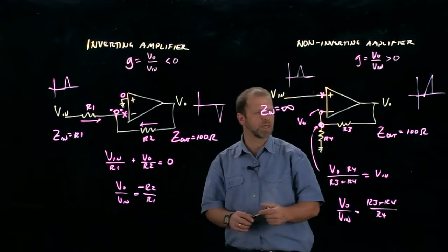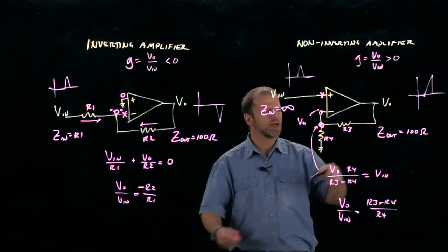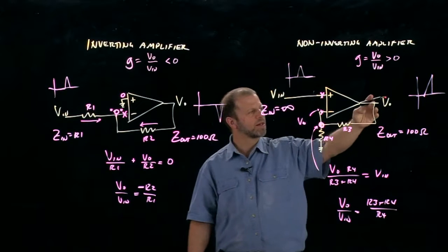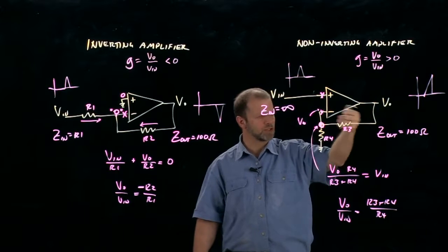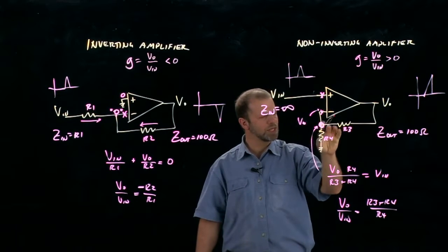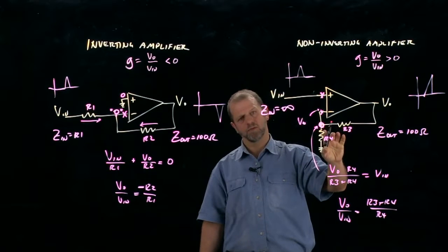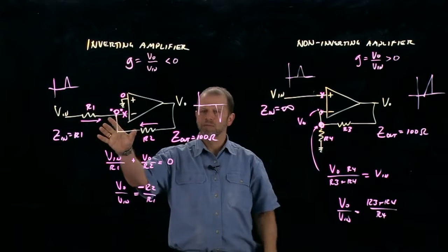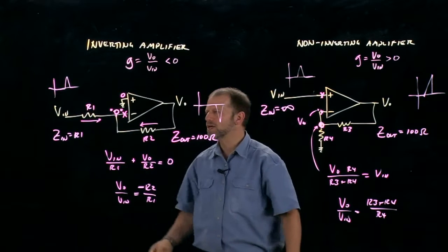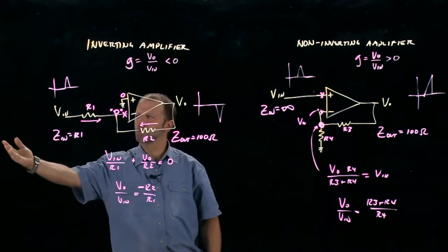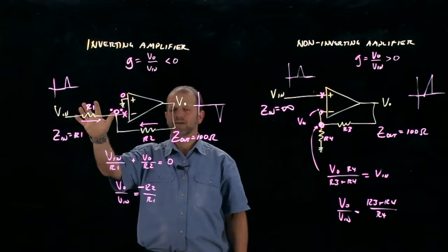Finally, let's just discuss picking sensible values for these things. You shouldn't use like 10 ohms and 3 ohms. The output of the op amp has to be able to drive this voltage divider, and you know its output impedance is like 100 ohms. So these things should be big compared to 100 ohms. And the kilo ohms, tens of kilo ohms, hundreds of kilo ohms. Same story here, but here it's doubly imperative because, in fact, the input impedances are 1. So because we're always doing low Z feeds high Z, it's really beneficial if R1 is pretty big.